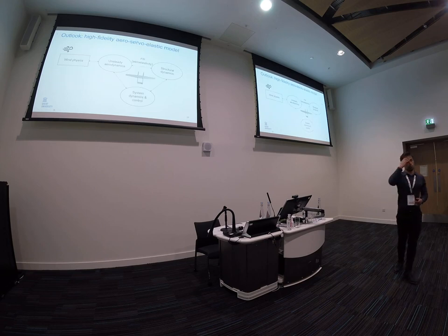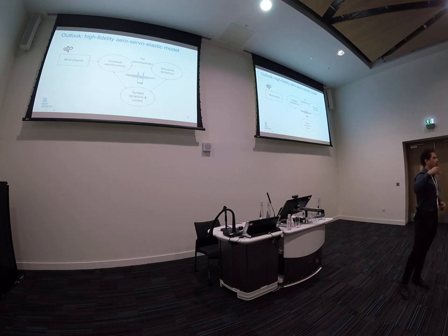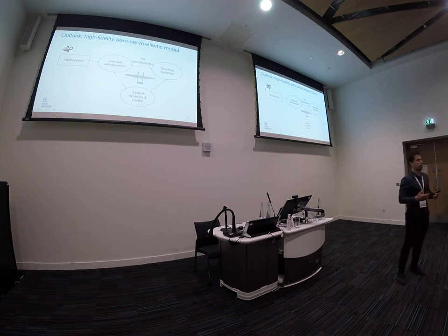Then an outlook to future work. So today I presented a one-way coupling from the system dynamics to the aerodynamic model. But in later work I also want to couple the forces back to the system dynamics, and also make a coupling with the structural dynamic model, which was already established in previous work. So the overall goal of this research is to develop a high-fidelity aeroservoelastic model, together also with my colleagues at Ghent University.